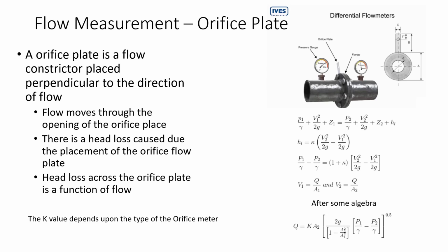way to measure flow, and the orifice plate takes up a much smaller footprint, so it is very small, so it works well in places where you cannot really contract and expand the flow back in a pipe. So if your pipe section is small and you don't have enough of a length to contract and expand your pipe and then expand it back, you make use of an orifice plate.